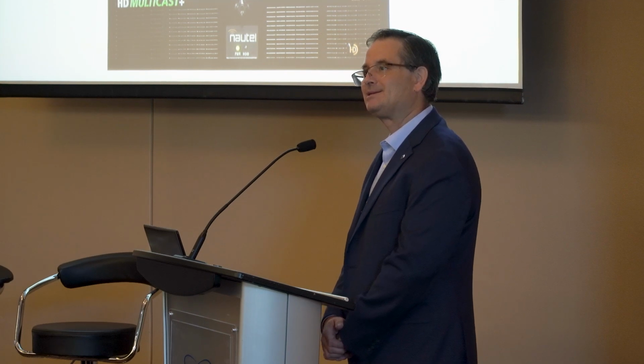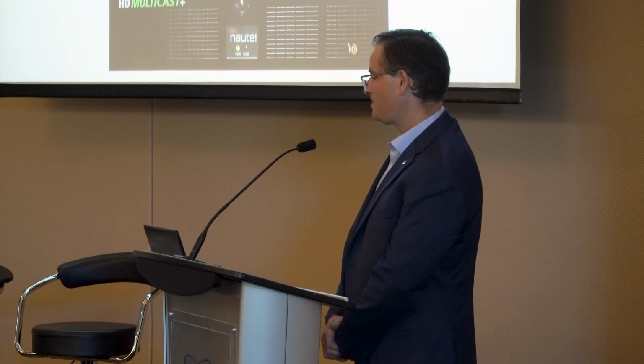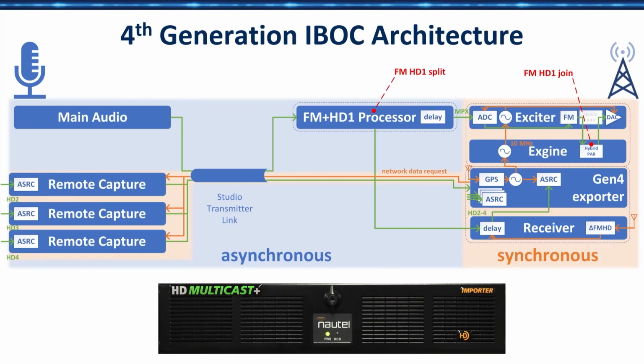But really, high-level architecturally, not much really changed. If you look at it from the 20,000-foot level, the equipment changed, the implementation changed, but fundamentally not that much. The addition that happened here is that we introduced receivers that look at the off-air signal, look at the time delay between FM and HD1, and can add a delay line to null out that delay. So that was one addition, not strictly related to that generation, but it's something that happened along the same time frame.